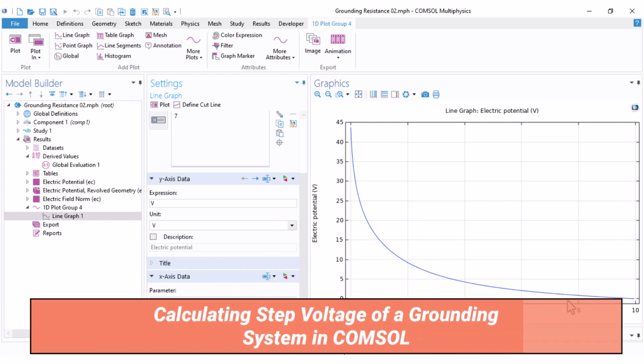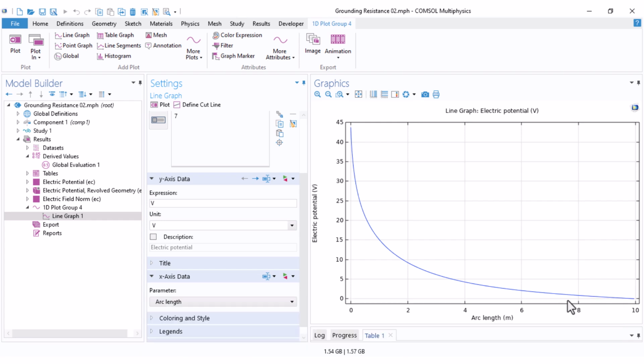Using this diagram, very simply, you can find the step voltage that happens on the surface of the ground. This is also a very important evaluation parameter for the grounding systems in high voltage substations and so on. For example, here, if someone stands here, one foot is on 10 volts and the other foot is on, for example, 2 volts. Therefore, a 2 volt voltage drop happens between the two legs, but this is for 1 ampere. 1 ampere exerts 2 volts. If 1 kiloamp goes through the ground, this 2 volts becomes 2 kV. It can be dangerous for people.